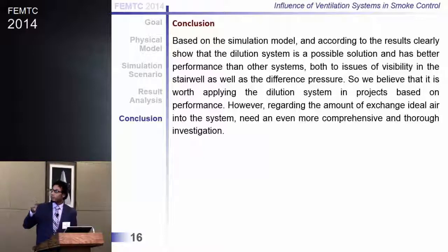And I'm talking about something about the evacuated people. For better evacuation, if we have a high building, we should make some space between the stairwell, to cut the stairwell, not make it so long, and make some space to break this stack effect. Because if you have some tunnel, you should break this in the middle and make some space, because the stack effect will be dangerous, because the pressurization doesn't let you open the door.